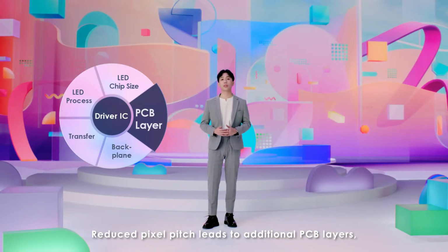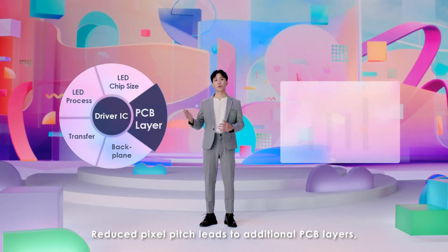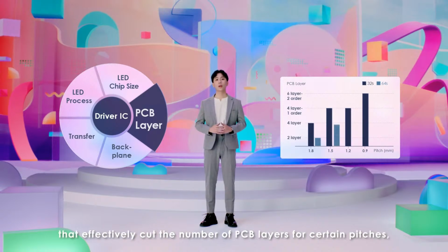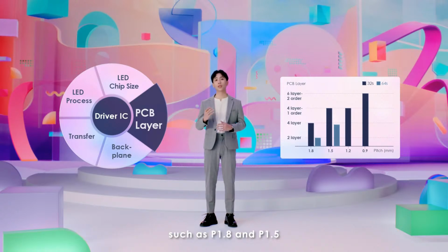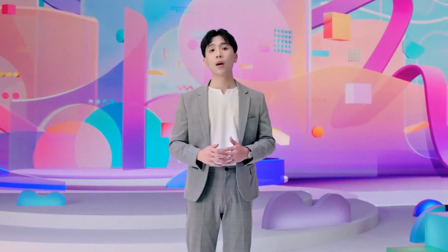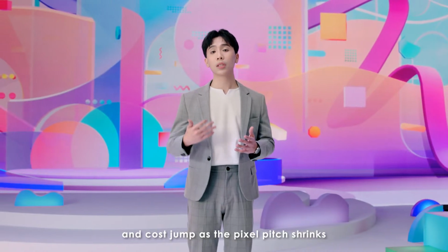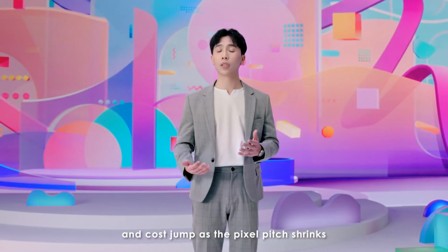Reduced pixel pitch leads to additional PCB layers, which increase manufacturing cost. Macroblock announced 64 scan products last year that effectively cut the number of PCB layers for certain pitches, such as P1.8 and P1.5. These factors show manufacturing technology and cost jump as the pixel pitch shrinks.